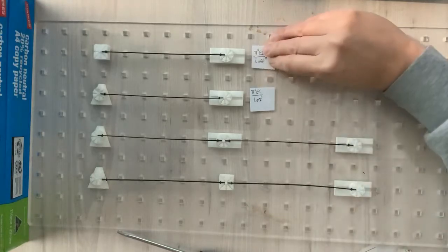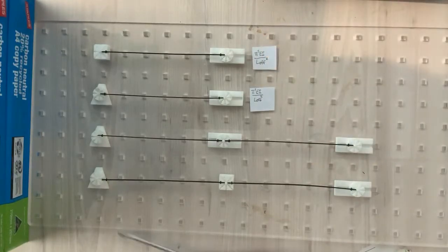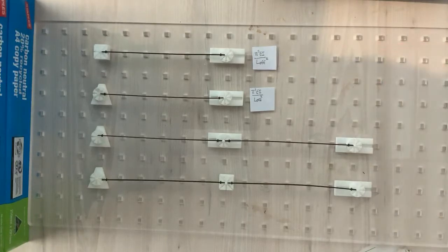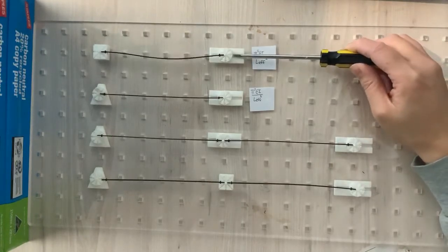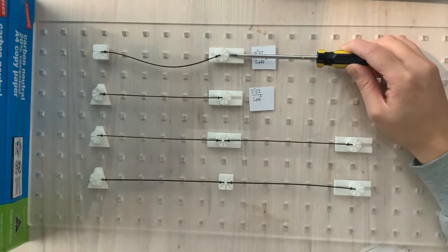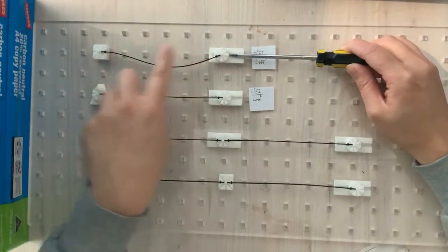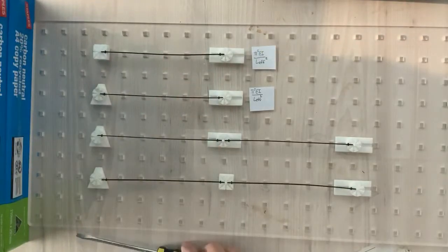This one we would also say is pi squared EI over the L effective squared, or the effective length. Remember, this time we get a buckled shape that we can see, and we can see that the effective length may not actually be the actual length of the beam column.